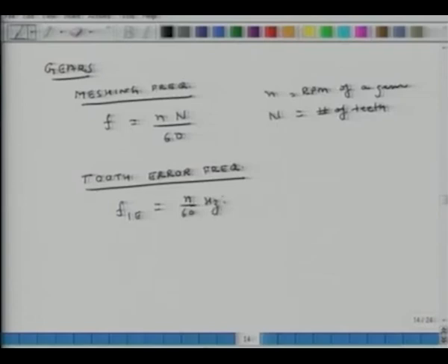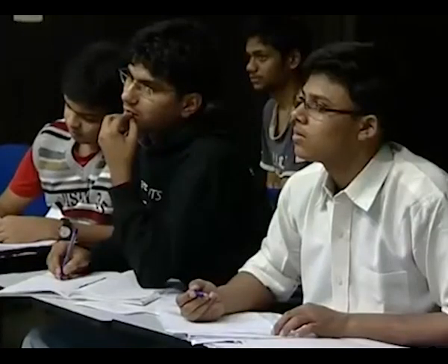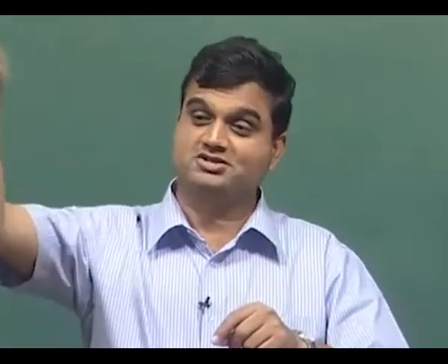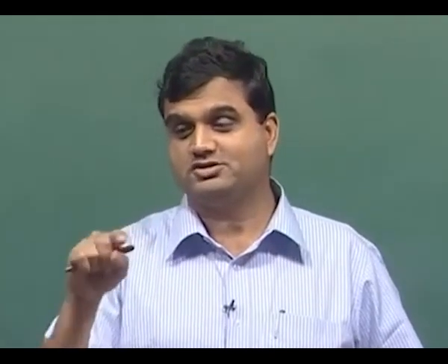Right. What happens if there are two teeth which are broken and they are next to each other? Will it be 2N? Or in that case, the other broken tooth has to be opposite at 180 degrees phase difference, right? Here you will have two impacts in one revolution, so it will not be just 2N, it will be a combination of different signals, right?